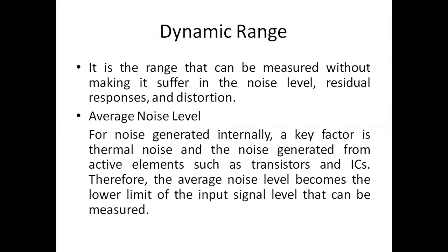And the final characteristic is dynamic range. So dynamic range is the range that can be measured without making any noise. That is the amount of signal that is measured from a noisy environment. So the noisy environment is characterized by 3 things. The first one is noise level, the next one is residual responses, and the final one is distortion.